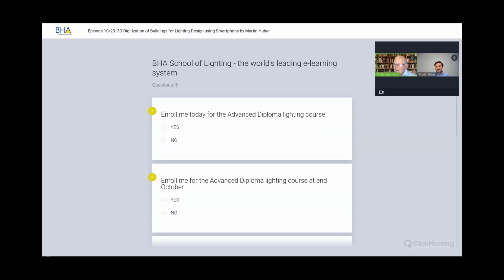One of the questions from Chinmay has already been answered, about Android applications. And can it be converted to 3ds format file? Not directly, but you could go through another software. For example, if you export a Collada file or an FBX, you can find a lot of software packages that allow you to then export into 3ds, but not natively. We don't natively write to 3ds, but you can go around via Collada or FBX.